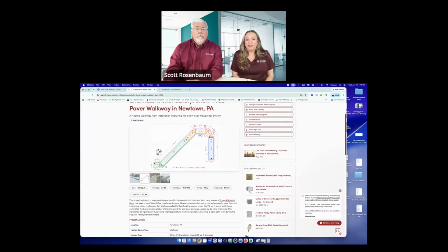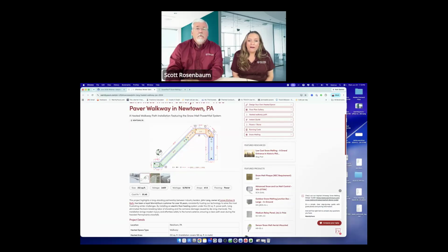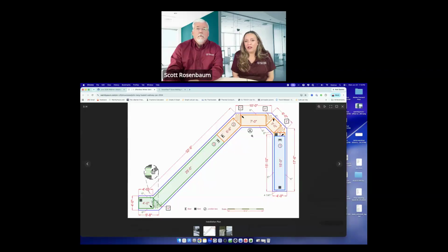So when you have a system that has straight runs plus a bend, it's so much easier to lay out the heating mats. What we do there is we show you how to cut and separate the long, straight, 3 foot wide run of mat and just pull off a little bit of that cable and hold it down to freeform it. So right there, we're telling you to take out 12 inches of the mesh netting, remove that and freeform up some of that cable. And on the other corner, we're doing 9 inches and another 9 inches to make those turns.